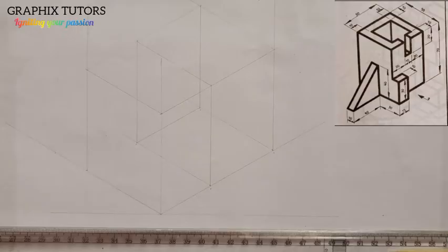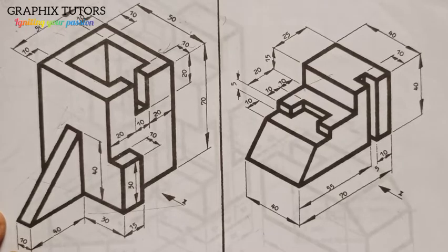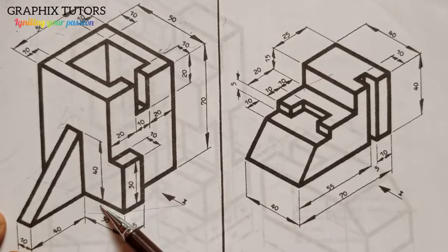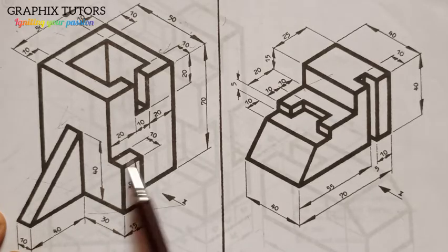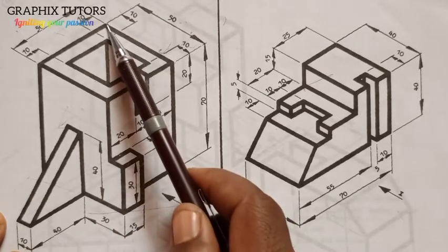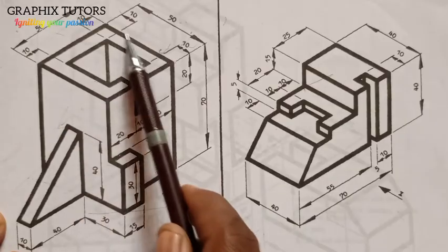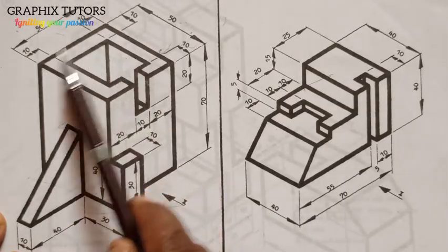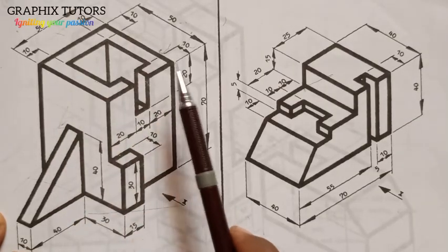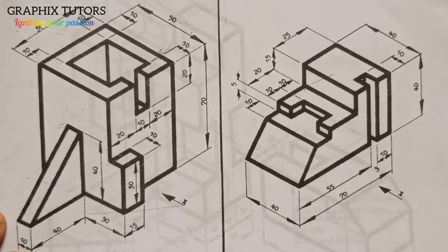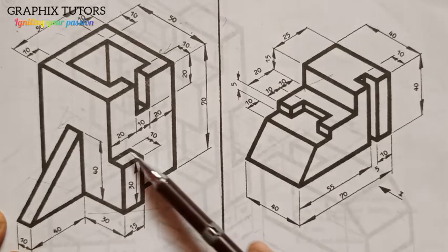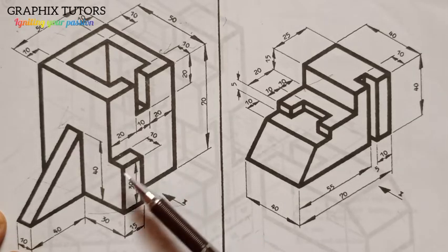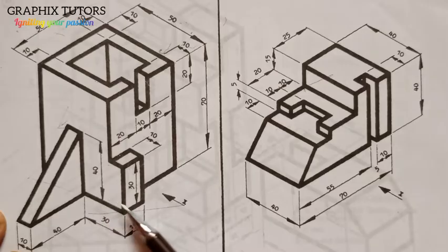Now if you look at this carefully, let's do this. I started from the back here and I measured 50. From the back here is thickened, and here also is thickened, including here. So I'll start from the back and thicken these four parts. But before I do that, I need to cut out this, which is 10. So I need to remove 10 from the x-axis, from this direction here.